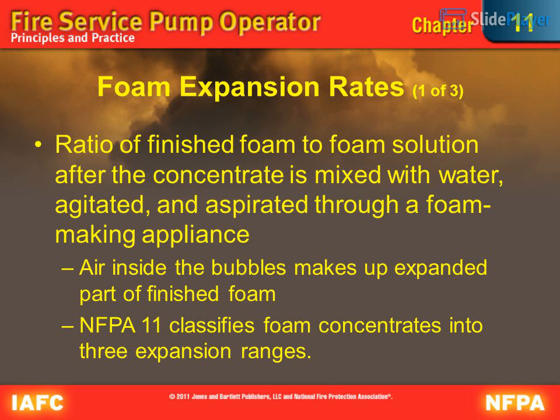Foam expansion rates, 1 of 3. Ratio of finished foam to foam solution after the concentrate is mixed with water, agitated, and aspirated through a foam-making appliance. Air inside the bubbles makes up expanded part of finished foam. NFPA 11 classifies foam concentrates into 3 expansion ranges.